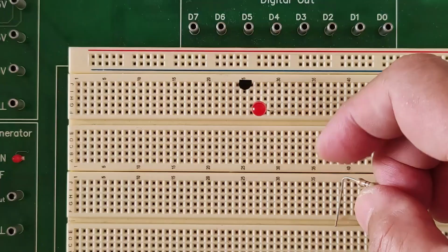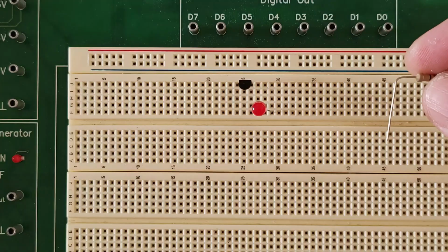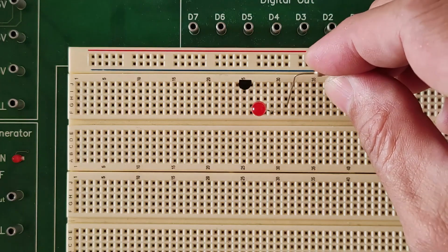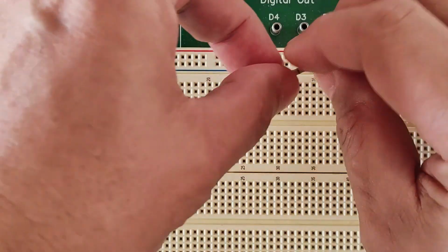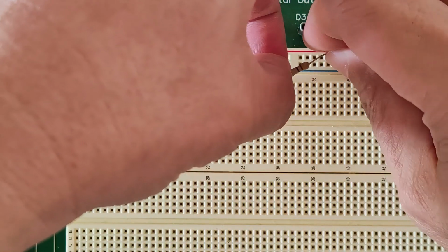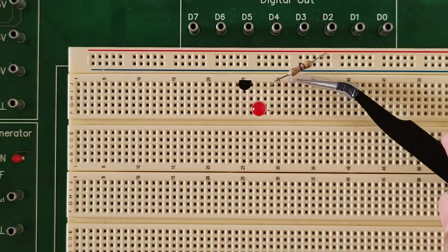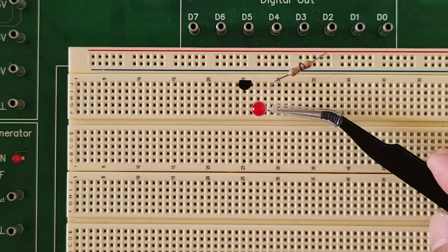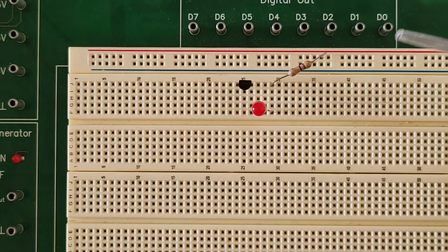Now, what I will do is this. The 470 ohm resistor, one leg is connected to the anode, and the other leg, if you could remember, is connected directly to the 5-volt source. So I'm going to connect one leg to the anode here, and the other leg to a power rail here at the top. I'm going to use the red power rail for that purpose. Like that. There. So this leg here is connected to the anode of the LED, and the other leg is connected to the power rail. On that power rail, later on, I will connect the positive terminal of our 5-volt source.